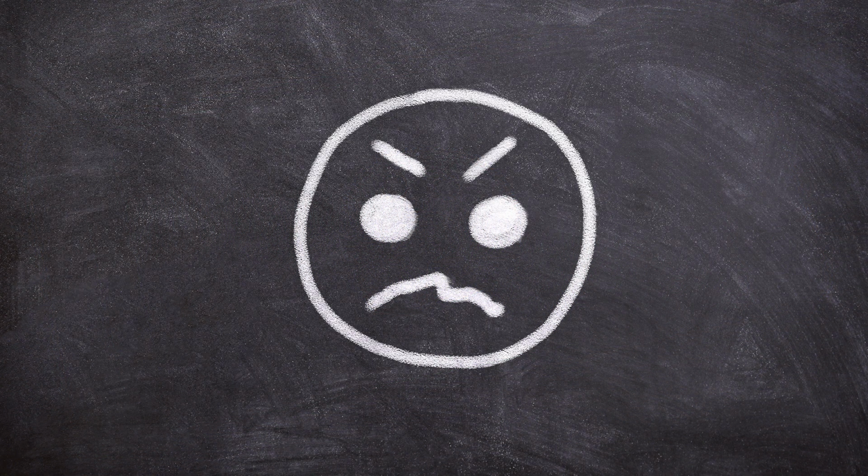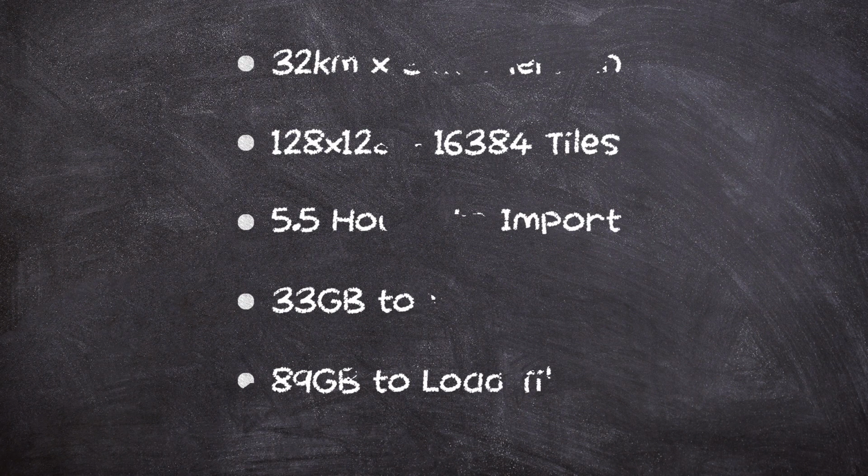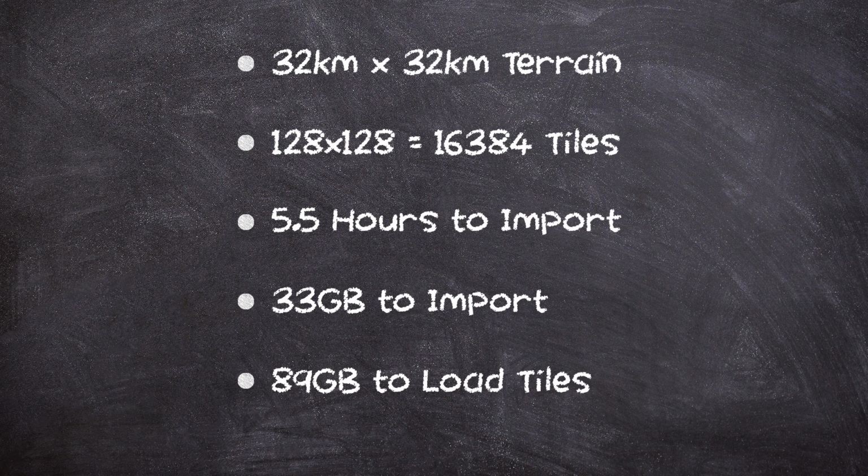I do not know if there is a maximum number of tiles that can be imported into world composition defined within the engine code. You will probably encounter running out of computer system memory or other editor crashes long before you can get to a high tile count. To test the Unreal Editor tile count maximums, I have successfully imported a 128 by 128 tile set, which is 16,384 total tiles, of 253 by 253 size tiles, which is a 32 km by 32 km terrain.